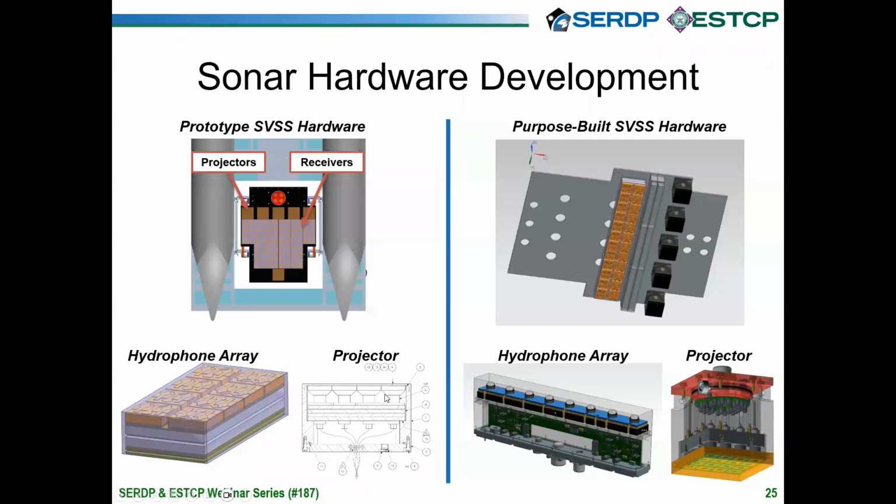So we had access to these individual elements that sit inside of our projector. These heads vibrate back and forth to push sound out into the water. And so we were able to leverage these existing internal elements shown here and then efficiently repackage them into a 4x4 grid, making up these brown squares here that are our sonar projectors.